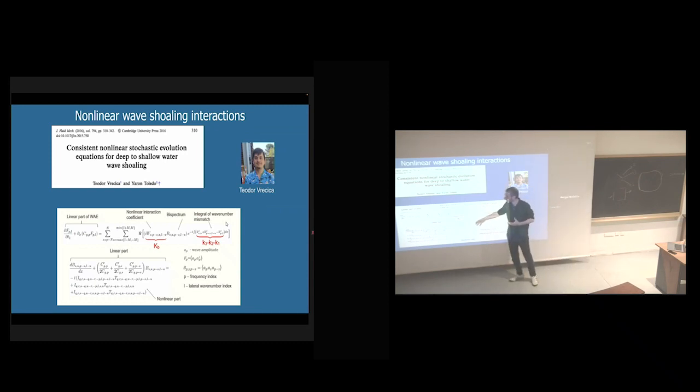Okay, so what is the procedure in order to get a source term here that is digestible? That was changing in the community, and there are the works of Eldeberky, who just neglected changes in the bottom, this flat bottom approximation. This doesn't change, and then we can just relate B to the spectra and substitute it here. And there was also an extension of it to all frequencies, because Eldeberky was for the second and fourth peak. And Becq-Girard, where is Michel, is he here? Yeah, so Michel, they derived this concept and did it with all interactions, so it was fitting also for infragravity.